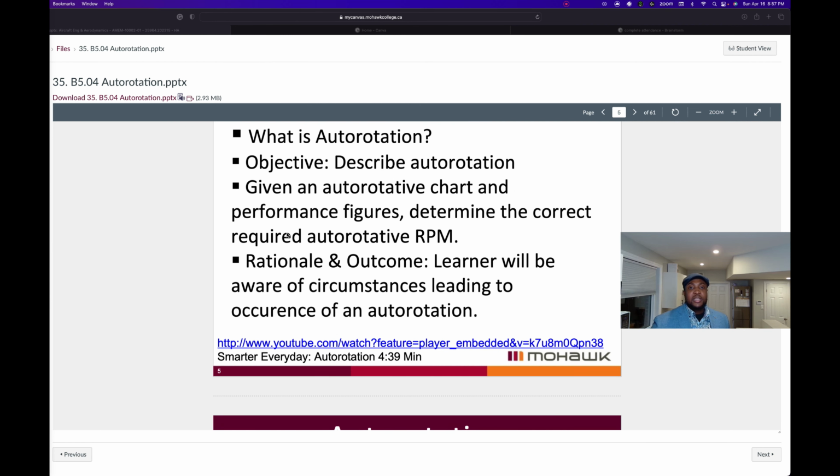It would not be advantageous to design all helicopters with high inertia rotor systems, because smaller helicopters would then be required to carry enormous weight, massive main rotors throughout their flight when it's not during autorotation. That's why you see that some helicopters will have a much smaller, lighter weight rotor system and may have a low inertia rotor system, because it's more efficient for powered flight.